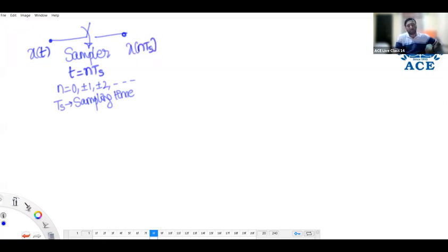So practically, what is this sampler? It is like a switch. We are using a switch for on and off. In a similar way, if you want to select the amplitude of the signal, close it. If you don't want to select, open it. It is acting like a simple switch. Why Ts comes into the picture is, we don't always want uniform separation of one sample. Certain times you want alternation of 3 samples, certain times alternation of 5 samples. That is decided by Ts, based on the gap we want.